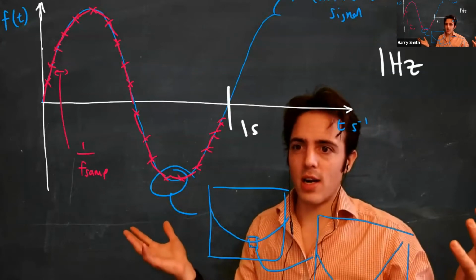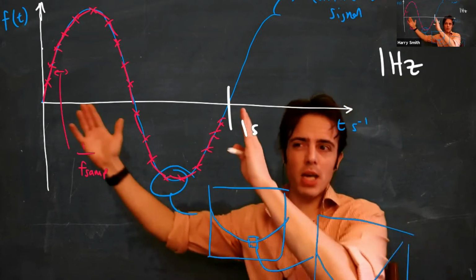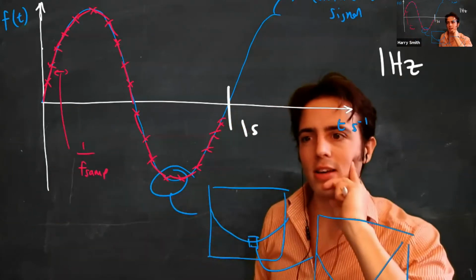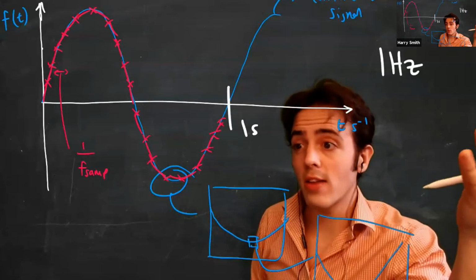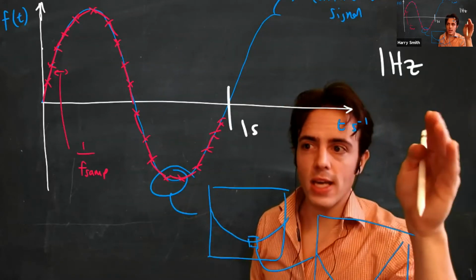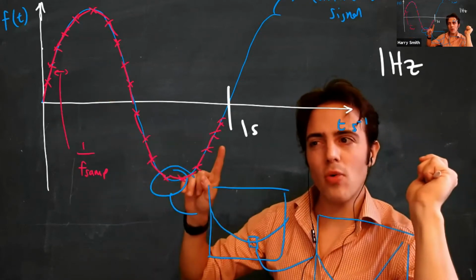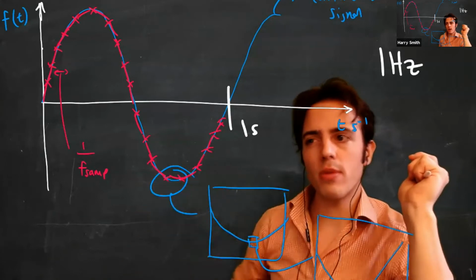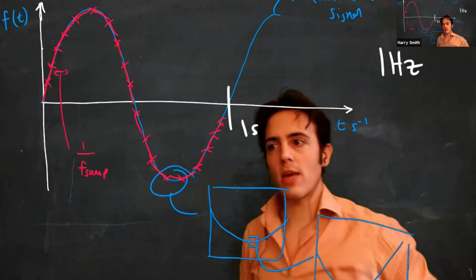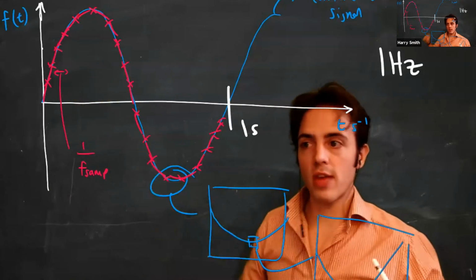And if I take all that data, I've got to record it somewhere, and I'm probably going to record for an interval longer than 1 second. So I don't want to take too many samples. In the interest of avoiding oversampling, we want to work out the lowest number of samples I can get away with and still determine the frequency content of this signal.